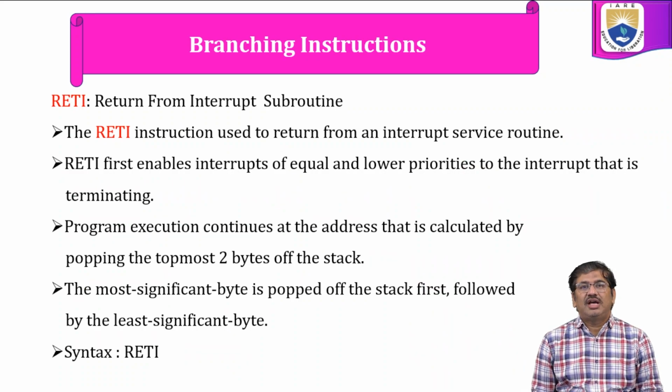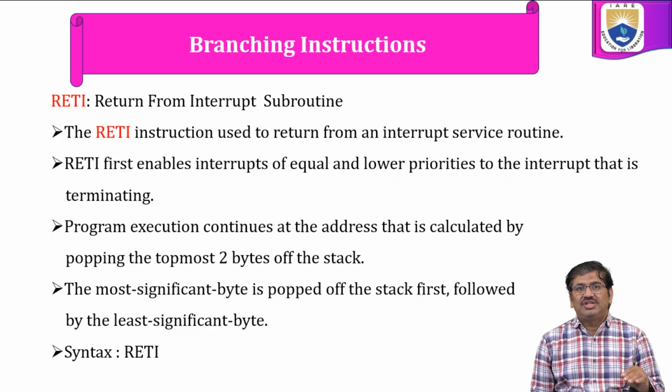The next instruction is RETI, which is return from interrupt subroutine. The RETI instruction is used to return from an interrupt subroutine or service routine. The RET instruction we write as the last instruction for a normal subroutine, whereas RETI we write as the last instruction for a subroutine corresponding to a particular interrupt, that is, an interrupt service routine.